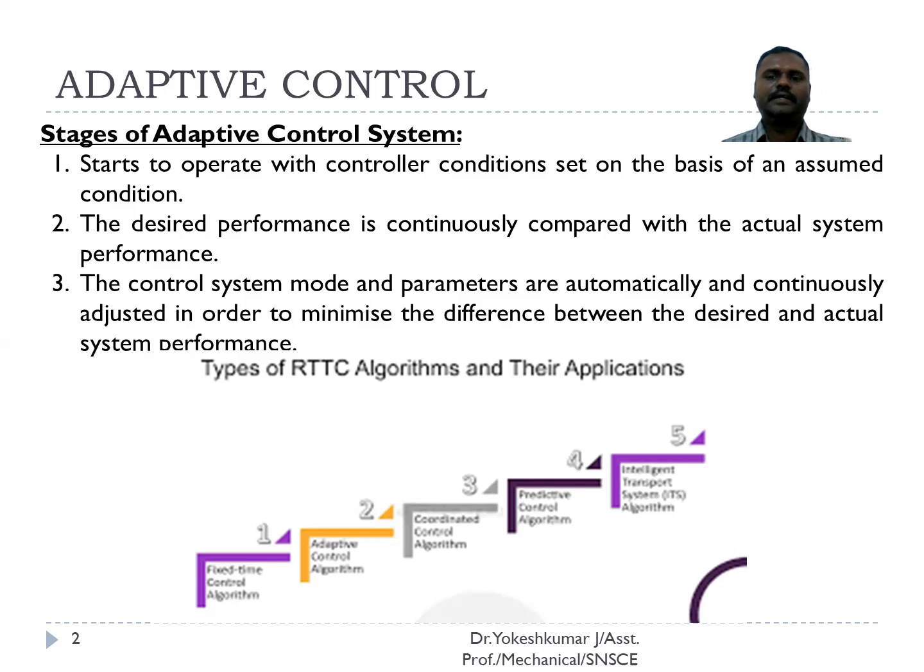Say, for example, the actual performance of the system, the temperature is around 30 degrees centigrade after cooling, and the relative humidity is about 65%. It compares this with the preset values. We already set the temperature of 26 degrees centigrade and the preset relative humidity of 55%. If there is any deviation, to meet the deviation it gives additional signals or changes the correction factors, and those correction factors and additional signals are sent to the control system so that the control system can operate effectively.